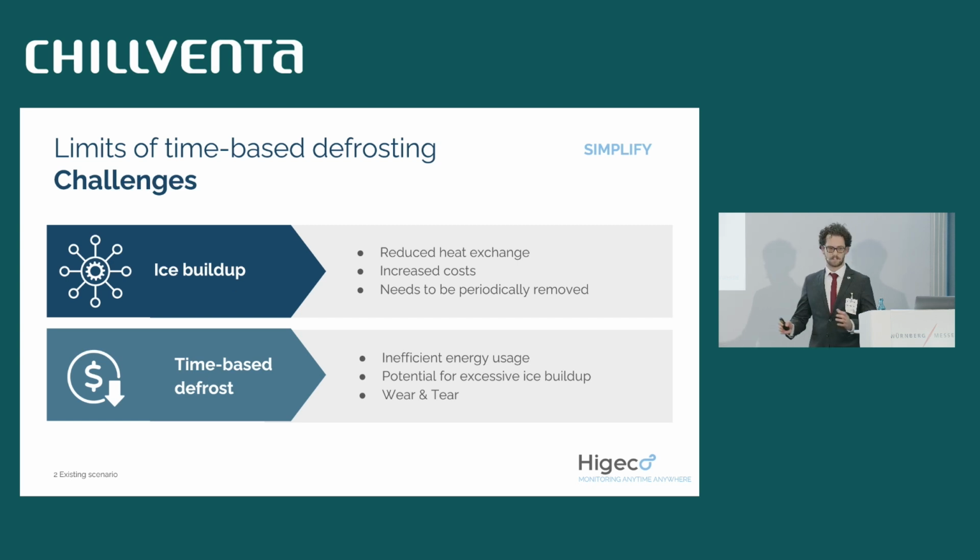So the existing scenario is, as you know, in refrigeration, we have ice buildup on the evaporator. This is problematic since as ice builds up, we start reducing its exchange, which in turn increases the costs of operation. And so we need to periodically remove this ice, either manually or through some defrost system, which typically is operated at regular intervals. So we have time-based defrost.